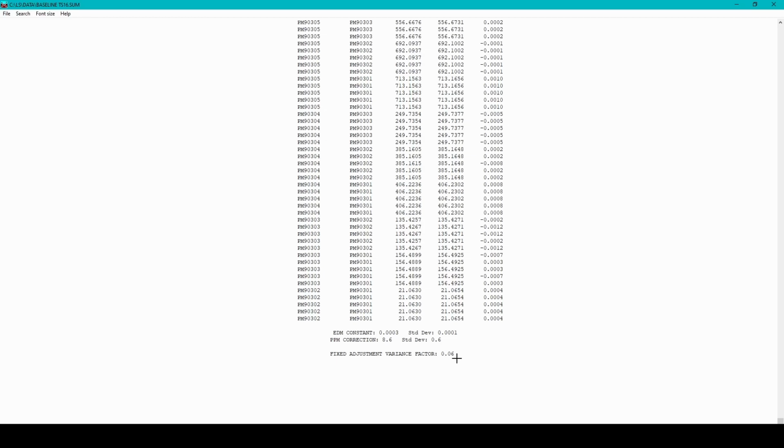The Surveying and Spatial Information Regulation requires that any length stated by a surveyor should not differ from the true value by more than plus or minus 10 mm plus 50 ppm. And this is to include uncertainty from all possible sources.